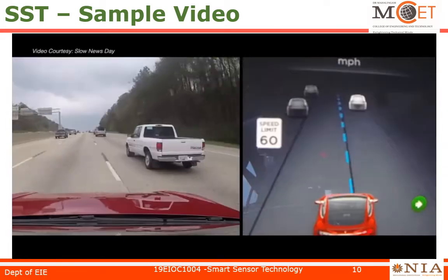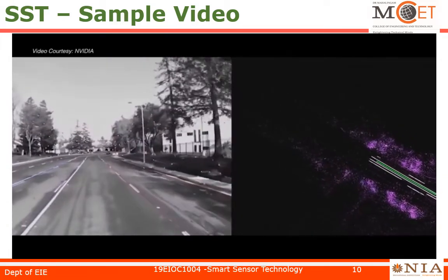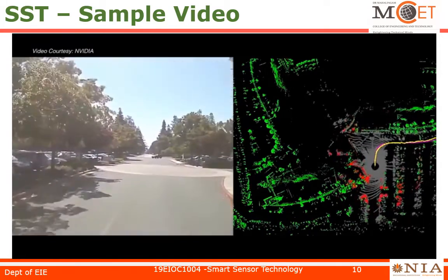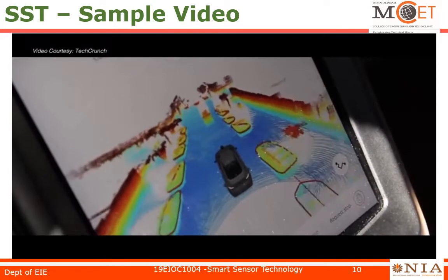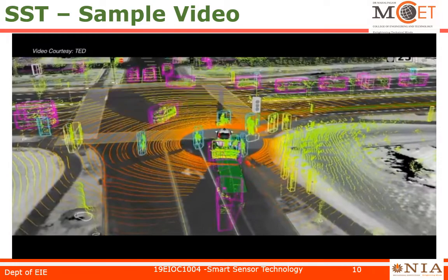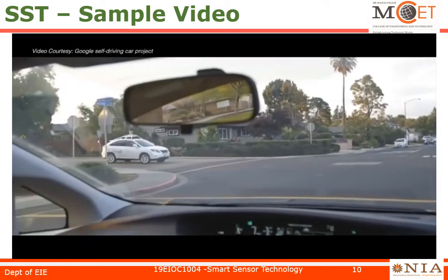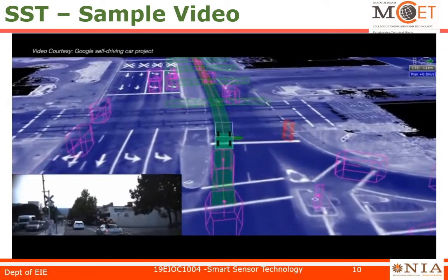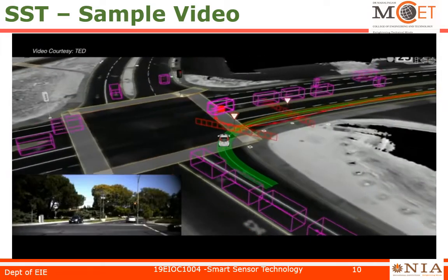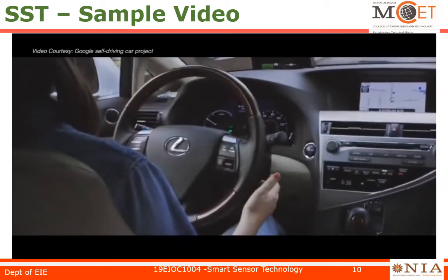An onboard computer records each laser's reflection point and translates this rapidly updating point cloud into an animated 3D representation. The 3D representation is created by measuring the speed of light and the distance covered by it, which helps to determine the vehicle's position with respect to the objects surrounding it. The 3D representation also monitors the distance between the vehicles that pass by and any other vehicle in front. It also helps to command the brakes in order to slow down or stop the vehicle. When the road ahead is clear, it can also allow the vehicle to speed up.